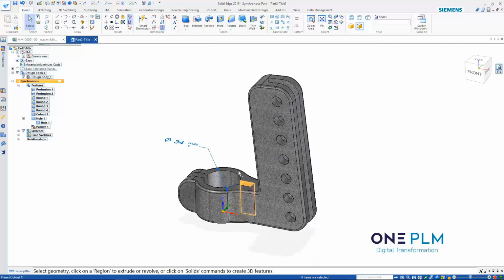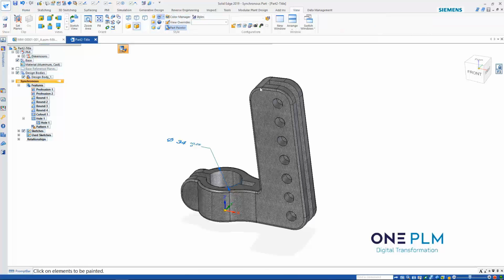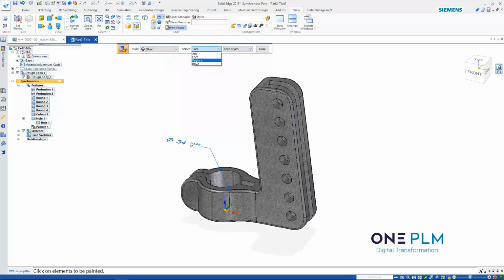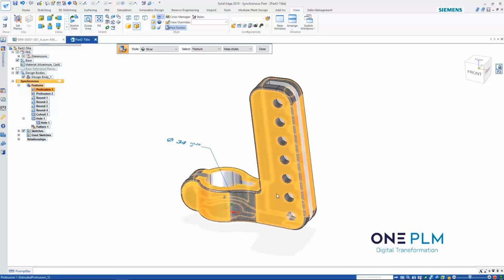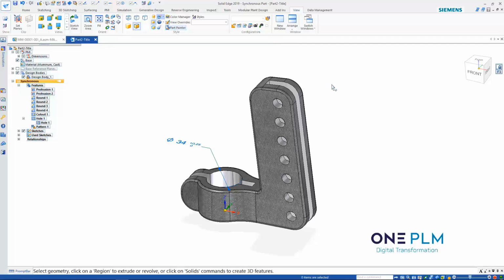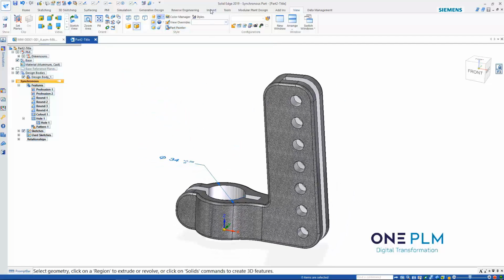We've actually got some machine parts on there. So I want to be able to show a nice view on my drawing like this. So what I'm going to do, I'm just going to paint those. So I'm just going to find a nice silver, nice little option on there. Notice we can paint features as well. So if I select the cut, I want the entire cut out to be silver. Select the whole. And we can get the pattern from there. So notice we've got features in our history on there. So that allows me to do that pattern on there. So that's showing all those. There's all the machine surfaces that I want.